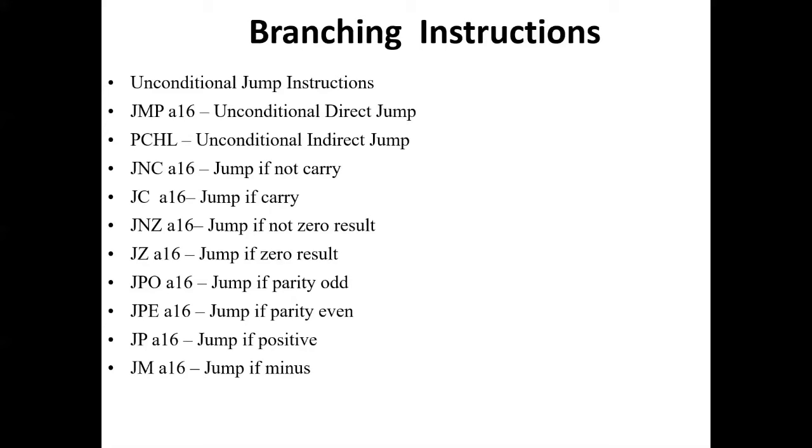But JNC F950H instruction execution results in loading of PC with the value F950H only if carry flag value is 0. Hence, after execution of JNC F950H, the instruction at memory location F950H will be fetched and executed only if carry flag value is 0.